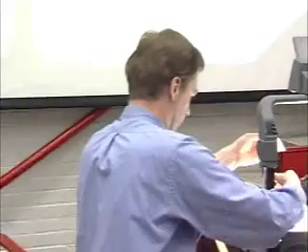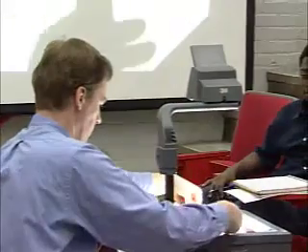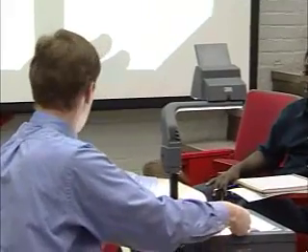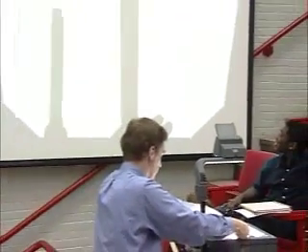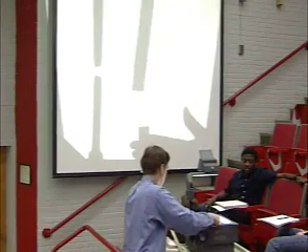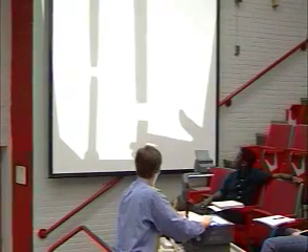I'm going to do another tensile test, but this time on a piece of aluminum, or aluminium where I come from. And I think I can manage this one on my own. I'm going to pull this, and you can see, oops, that's actually not necking. That's, oh, right, OK, there it goes. Always fails near the grips. That it bent up on me because I wasn't holding it flat.